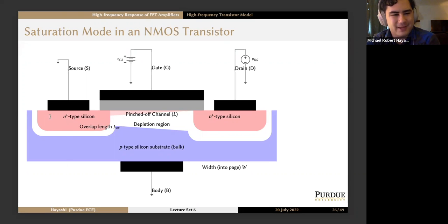The one coming out of the page, the one on the left of the source region, behind the source region, coming out of the page in the drain region, to the right of the drain region, behind the drain region. But you don't get it from the 4th side wall, the one that faces the channel, because generally the depletion is very large, so you don't even bother figuring out that capacitance contribution.